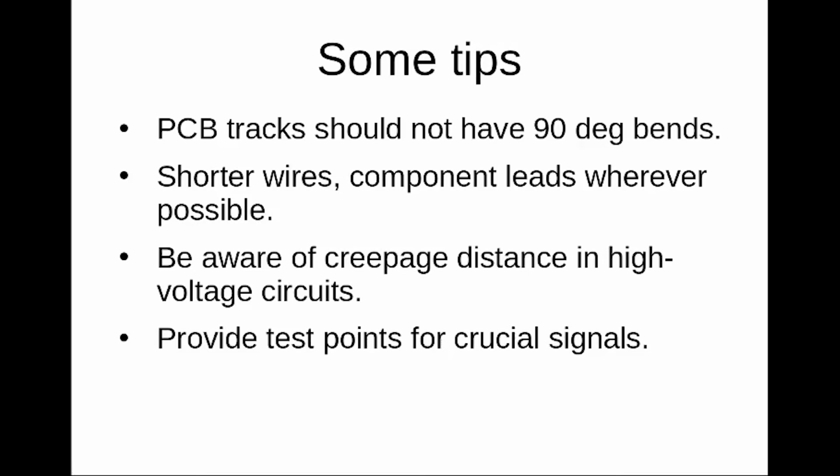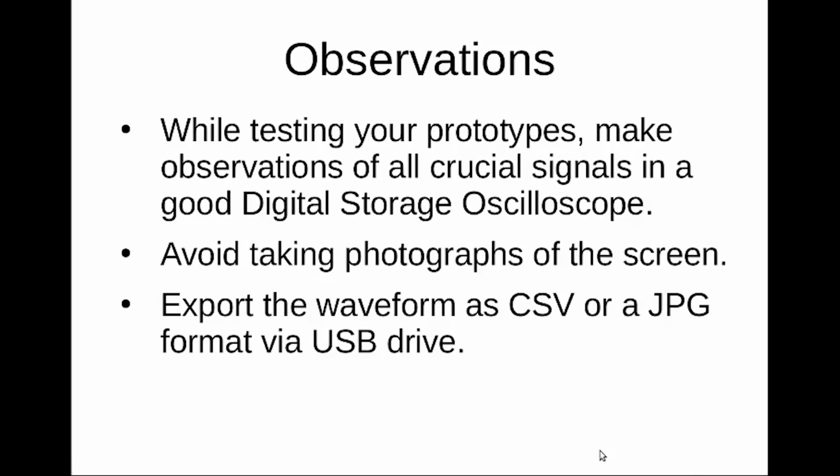When prototyping, whether it is in PCBs or in breadboards or general purpose PCBs, always use shorter wires and leads of components to avoid issues due to parasitic inductances. And don't forget to provide test points for crucial signals. And of course, as I told earlier, be aware of the creepage distance in high voltage circuits.